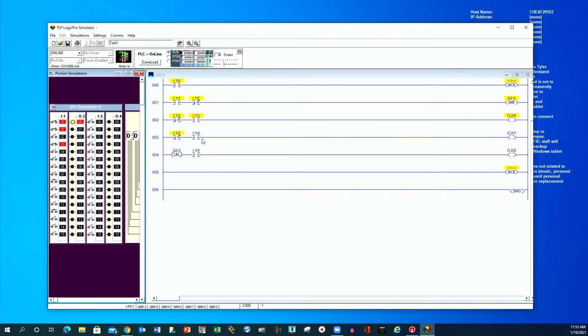It goes back. But I could make a conditional return somewhere and say, okay, I want you to return on rung 3 because I don't want to read rung 4, 5, and 6. I want to leave early. And this doesn't make much sense with a short one, but if you had a super long one, maybe whatever that subroutine was meant to do was already accomplished. So you don't need to keep on doing whatever is down the rung. So you can say return, and it will return back to its main thing.